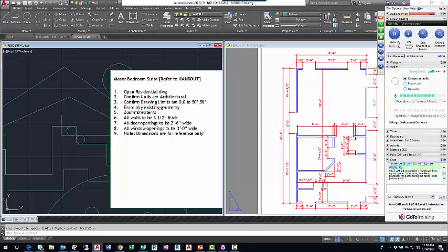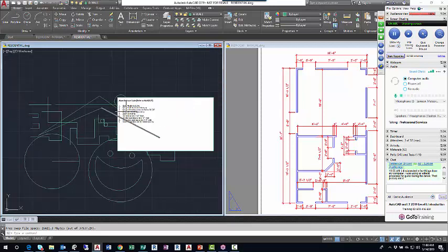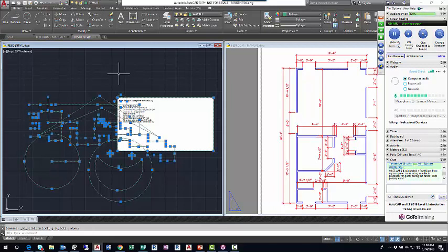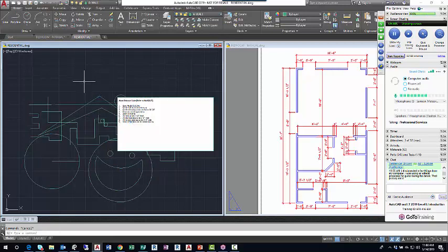So next up, it says to erase any existing geometry. So I've got a lot of line work in my drawing. I'm just going to do a Control A. Control A selects everything that is not locked or frozen. And we didn't talk too heavily about locked or frozen, but the layers have a locking icon. I'm going to say all my stuff is on the A wall layer. If A wall were locked or frozen, none of this stuff could be deleted. I'd have to unlock and unfreeze.